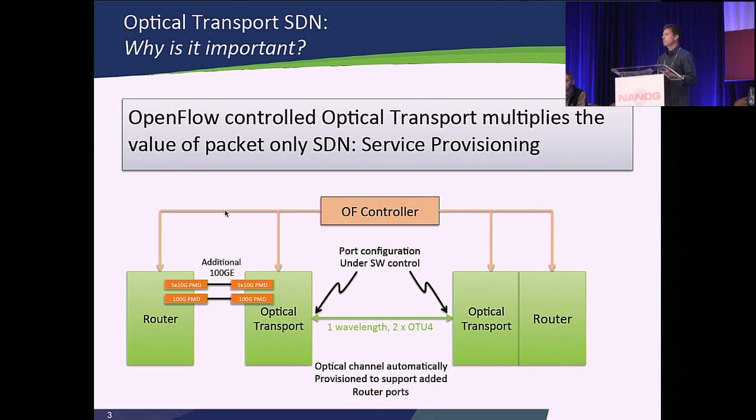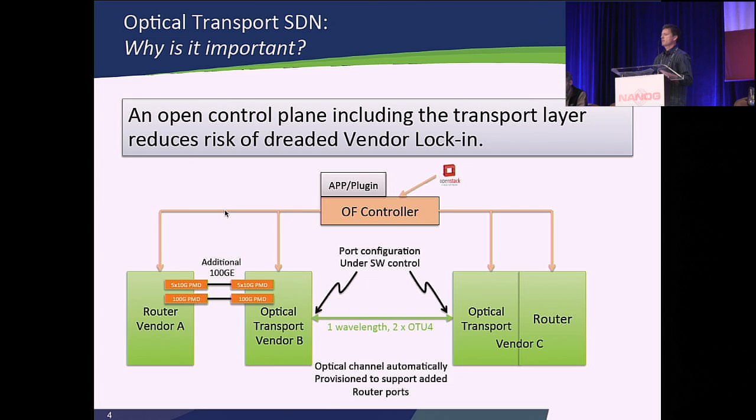So you might ask, why wouldn't you simply configure this port and leave it nailed up to 200 gig in the first place? And the answer to that is actually power. The higher modulation formats are actually quite power hungry. And if you were to do it across your network, you would impact your power budget quite substantially. So having a dynamic approach to the port speed and configuration can actually save power. Another aspect that's valuable is